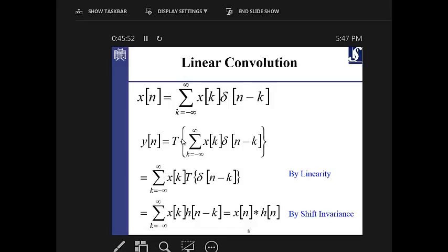If you know this, the filter is not changing. That's the system. It's already fixed with its parameters. You set the parameters. That's all. After tuning the parameters, you just let it go. And input is coming. Stream of input is coming. If you know the system already, then by knowing the input, you should definitely know the output if the system is linear shift invariant. That's the beauty of the linear systems. And that's why people in mathematics and many other fields of engineering try to model every natural phenomenon, even by linear systems. Because only linear systems have this property.